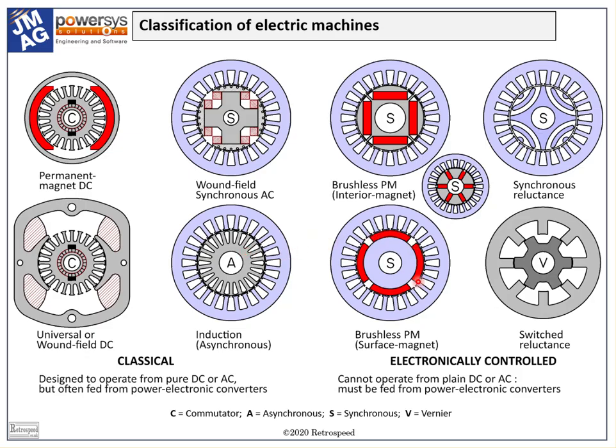This surface magnet motor, or SPM, is here in the chart. The IPM and SPM are closely related, brushless AC synchronous permanent magnet machines. They have different speed-torque characteristics, but they share the same high efficiency. And of course the rotors are completely free from commutators or slip rings, and they do run cool. Shaft position sensors are often used, but these don't wear out in the same way that brushes do, and they don't introduce friction, heat, or noise.